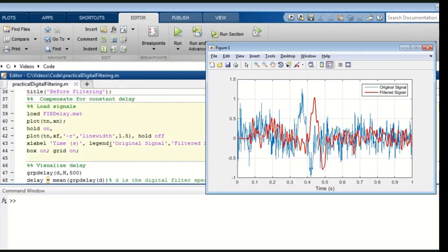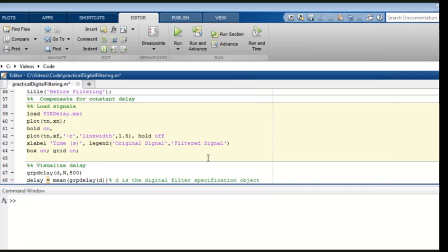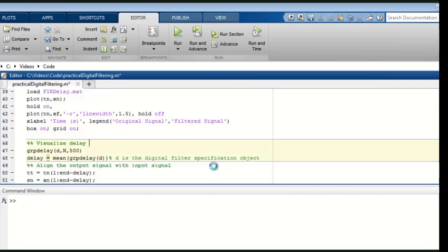The blue line represents the original signal, while the smooth red line shows the result of passing the original signal through a low-pass FIR filter. The process removed sharp variations in the original signal, but clearly introduced a delay that time-shifted the output with respect to the input. The grpdelay function allows us to determine the nature of the delay introduced by the filter.